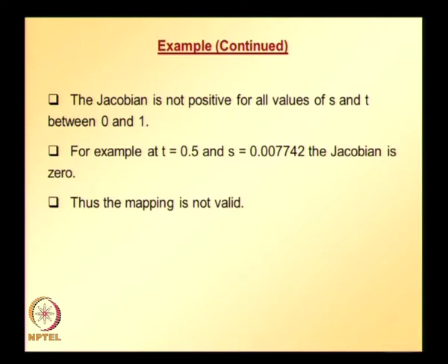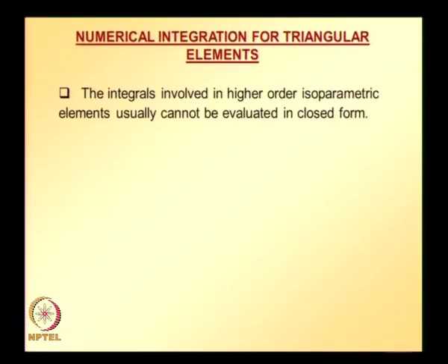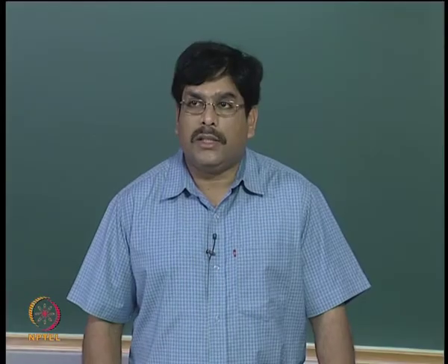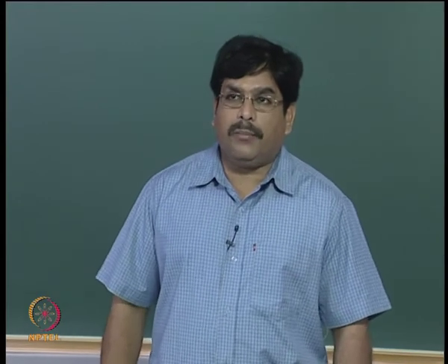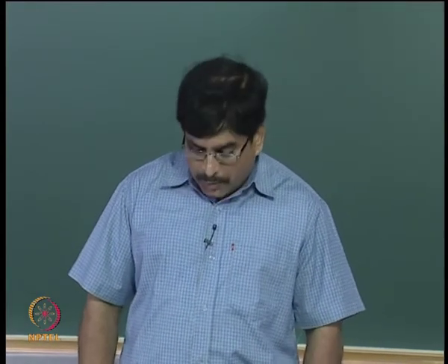And now let us go to the other concept, that is numerical integration for triangles. When we have integrals, especially for higher order elements, the integrals that we usually encounter are not going to be very simple integrals, sometimes we need to adopt numerical integration.